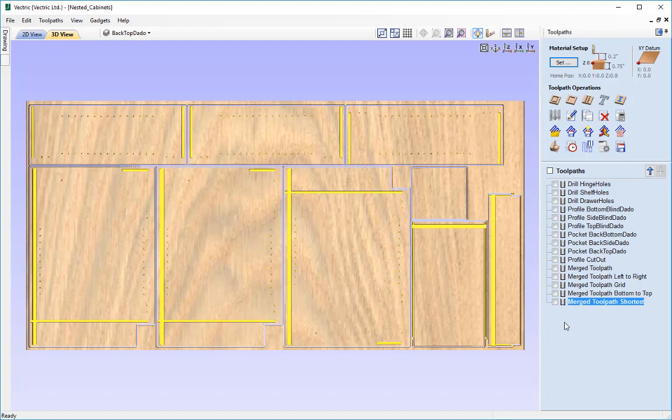If we would like more control over the toolpaths, whether we're cutting a singular part or a multi-part design like our nested cabinets example, then we can achieve that with a bit of extra work up front, where we would have to organise our vectors and toolpaths for all of our parts first, and then utilise the ordering system of the merged toolpath to gain extra control over the way they are run, whether it be for pure speed or the fact we want to have our CNC finish the toolpaths for whole parts before moving on. The choices are there for us to make.